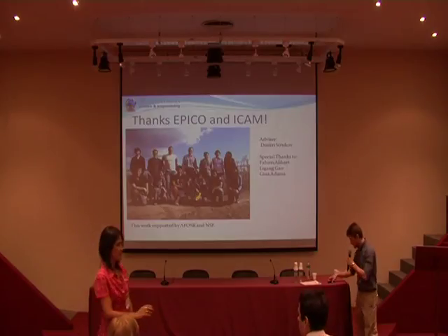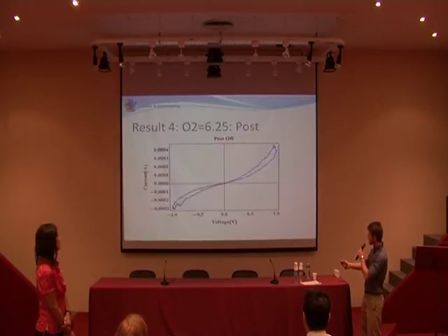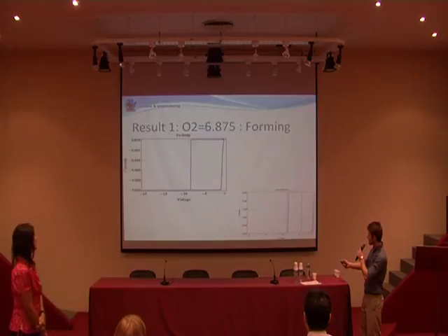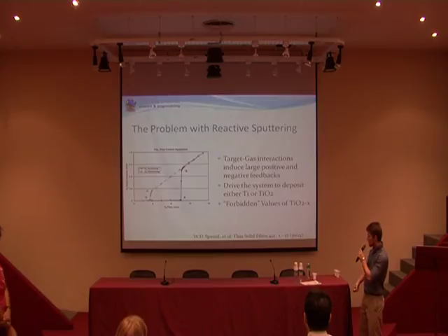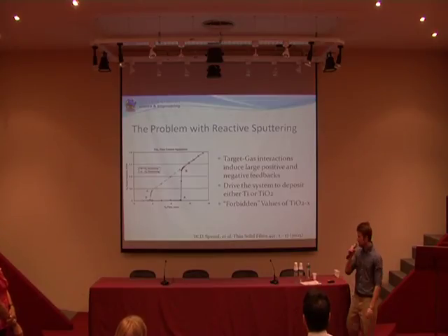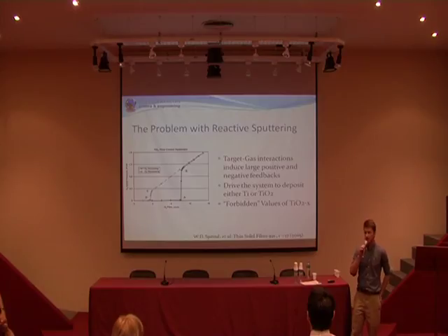So actually, in the previous study, I forget the guy's name, but I can go back. This guy, Spool. In general, in this region you have kind of an S-type hysteresis, which you are free to explore if you also have positive feedback on your mass flow rate controller. So there are options on the market at significant capital expense. You can basically just buy a residual gas analyzer, attach it to your system, and then have active feedback.